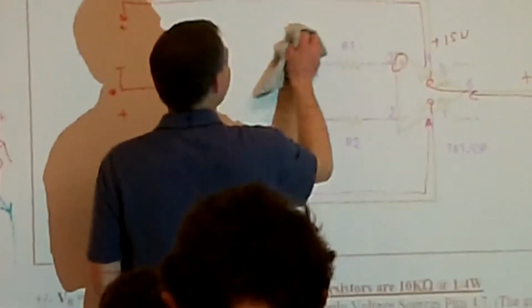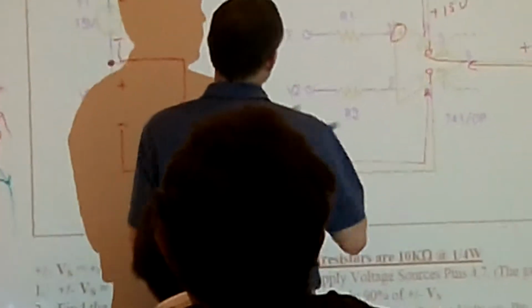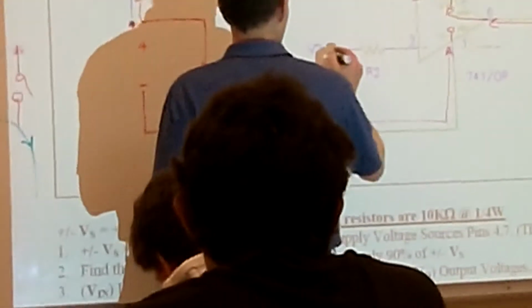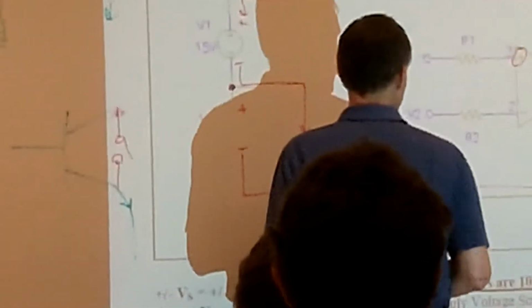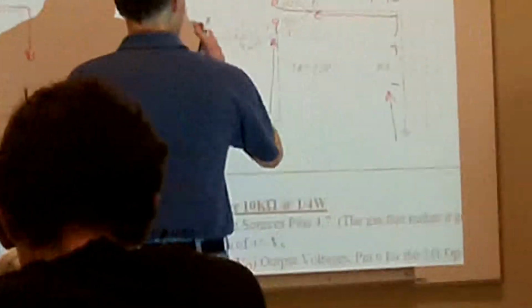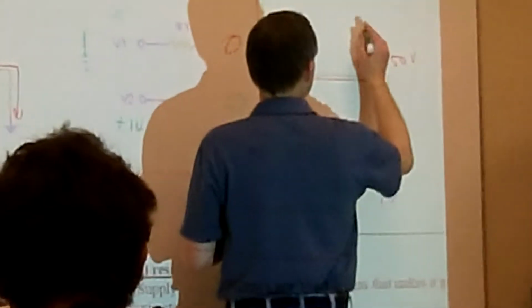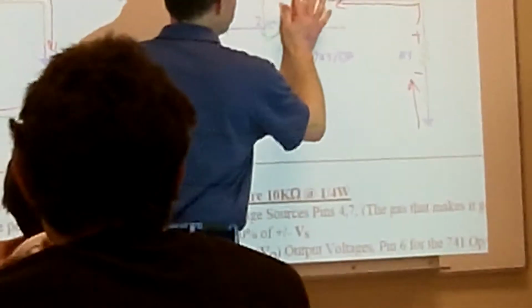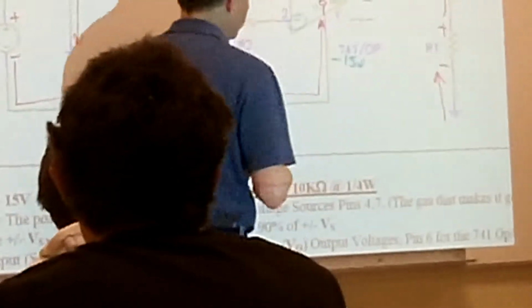Now if I go ahead and switch that around, and I go right out of the ground and I put plus 1 volt on V2, this time I'm more positive on my inverting input, so I know that my output is going to go to a negative 13.5 volts. My switch is going to switch and it's going to go down to my negative 15 volts VCC.